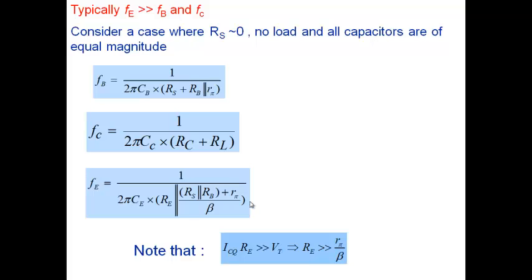Oh, sorry, how do I bring this term? I have to increase this particular term, right? How do I make this term large? Make RE large, right? But RE isn't in parallel with this one. So if you simply make RE large, what will happen is this term will become limiting. And which term do you think is important here?